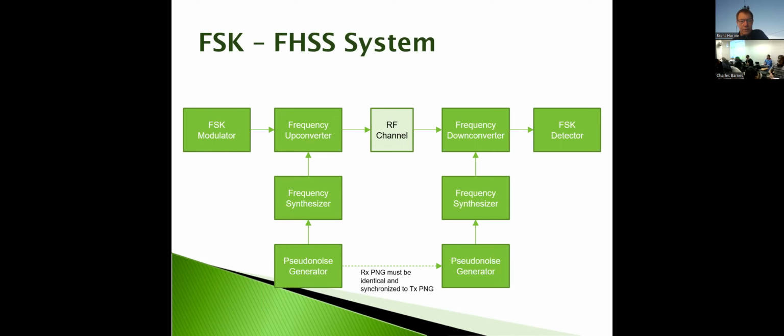So we have this system, the real distinction is the fact that we're tweaking this frequency source, what we maybe called a local oscillator in the past. Now it's a synthesizer, and we can program this very quickly, right? So you need something that can switch frequencies pretty quickly. So there are some engineering challenges there. We've got that solved these days, and then you're having this deterministic but noise-like